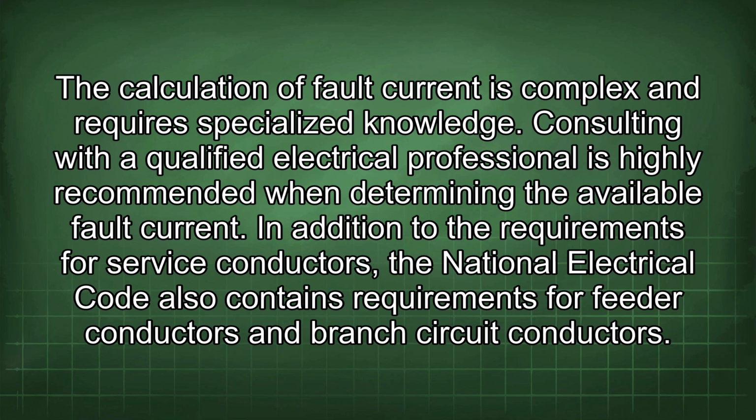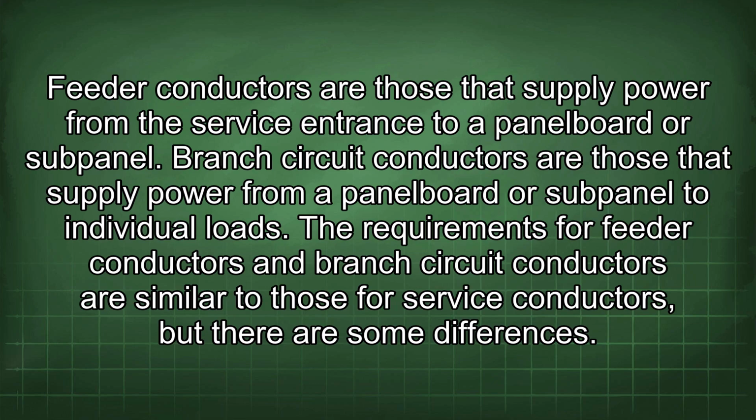In addition to the requirements for service conductors, the National Electrical Code also contains requirements for feeder conductors and branch circuit conductors. Feeder conductors are those that supply power from the service entrance to a panel board or subpanel. Branch circuit conductors are those that supply power from a panel board or subpanel to individual loads.